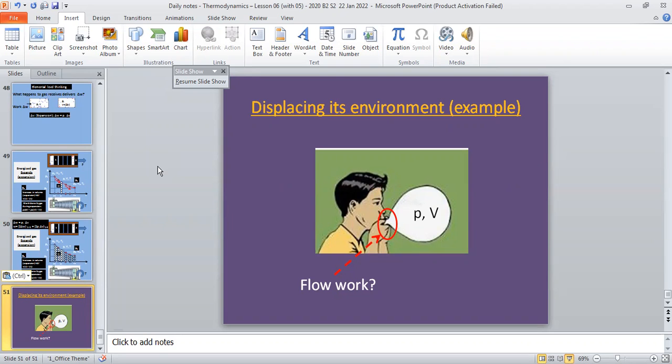Seeing delta W in this PV graph as a tiny strip, representing the area as P delta V, which is delta W, and using many P delta V's means finally the entire area underneath represents the work done during this expansion process. V changes, and there is delta W for initially high work done, finally less work done.